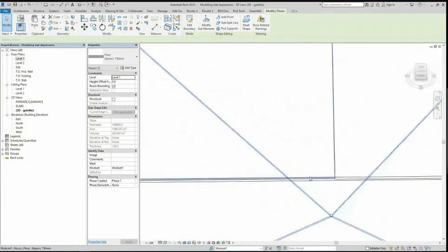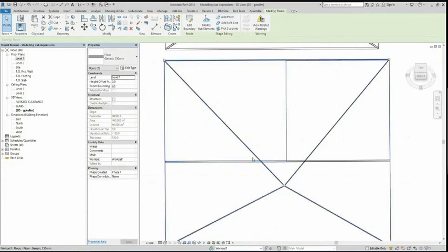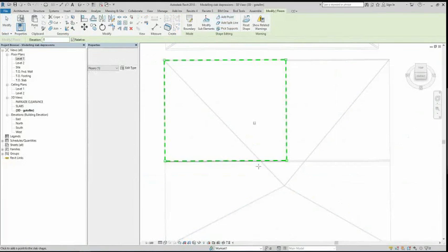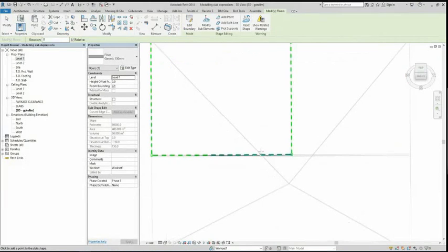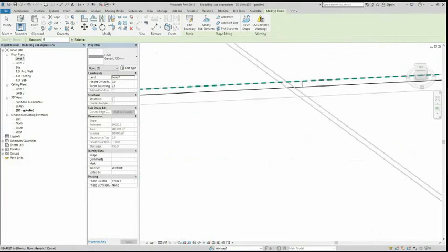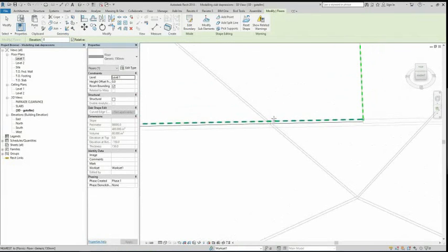So before I get started, I want to add points to each of the 3 floor elements that I was working on. So I'm going to start with the first one. I'm going to add a point, and the reason I'm doing it for this step is we're creating nodes or points along each slab that can then intersect the lines of the sacrificial slabs. So it's a little bit difficult to see here, but when I go through the steps, it'll make a bit more sense.